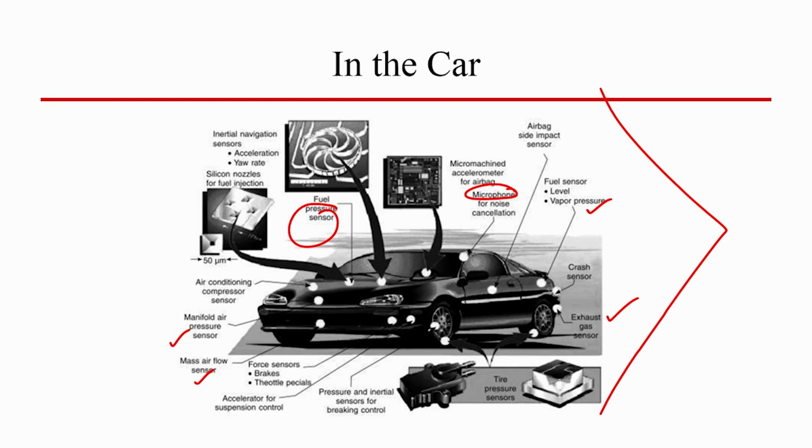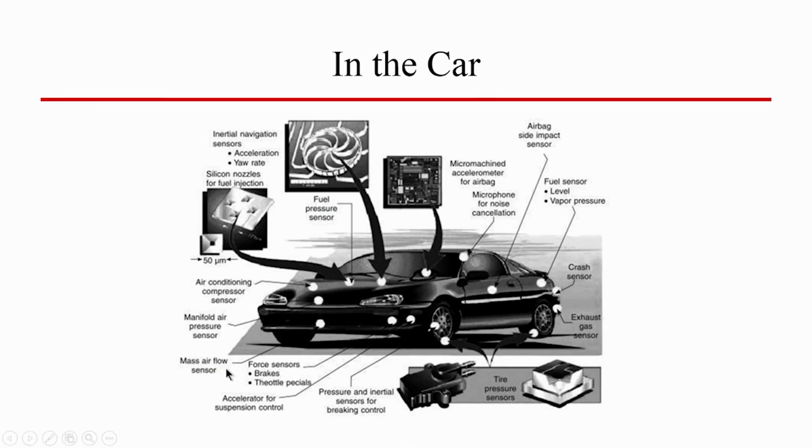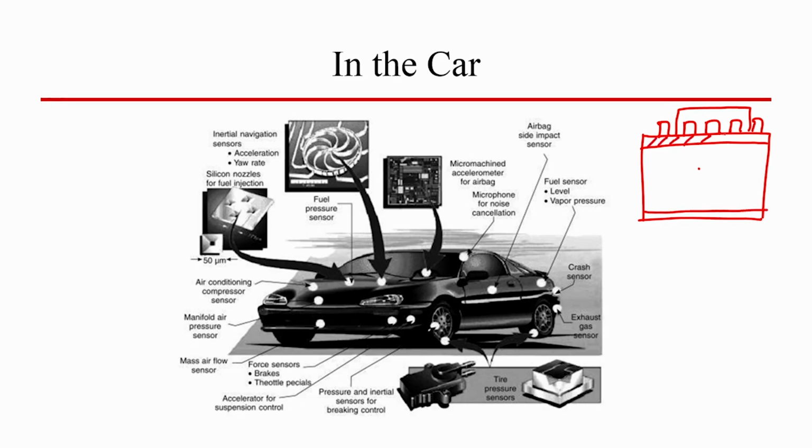Now, if we talk about gas sensors, it becomes very simple, and we have discussed it in one of the modules. If you want to design a gas sensor, what you require is a substrate, contact pads, and the sensing material on the contact pads. If it is silicon, then we say this is an oxidized silicon wafer.